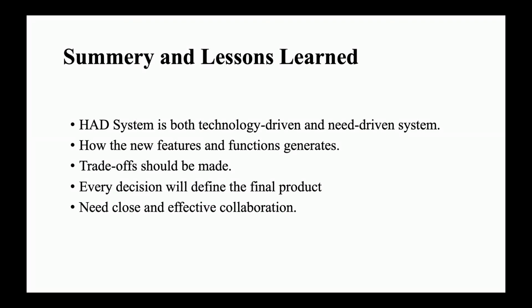There are trade-offs that should be made, such as the accuracy of inertial positioning is high and isn't affected by external signals, but the error gets bigger over time. Satellite positioning has more satellites but is easily affected by weather conditions. Lidar has a good sense of the surrounding environment, but the price is high and requires large development cost. Ultrasonic sensor information transmit speed is also easily affected by extreme weather conditions, but the technology is relatively mature and cheap for short range ranging.